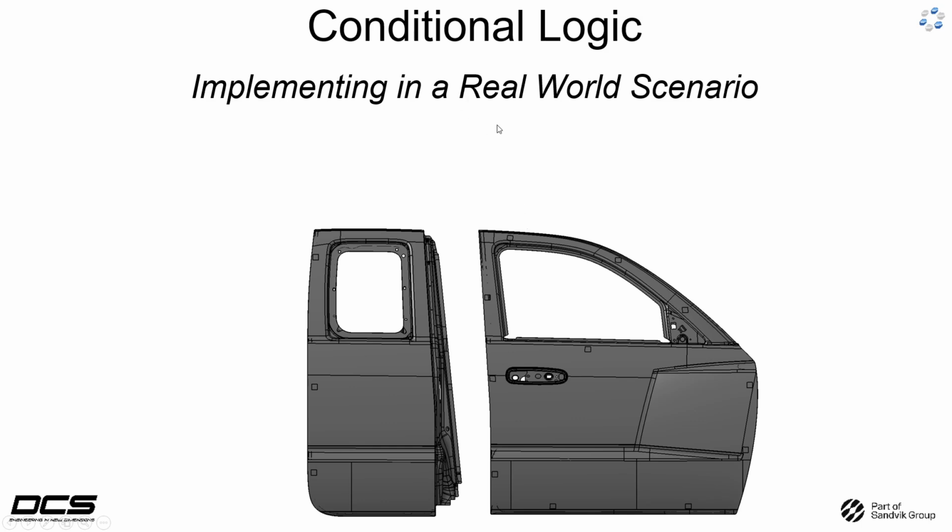So for this example, we have two door assemblies. And both door assemblies, when brought to the line, are located using a combination of fixture pads, here in yellow, and pins that go into holes and slots, respectively, here in the green and red arrows, for the secondary and tertiary controls. Likewise here for the front door.